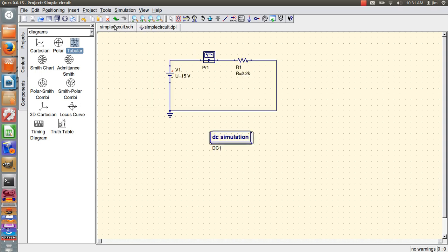and my voltage 15 volts, 2.2 k ohms, so just under 7 milliamps, which would be about right if I multiply it out. And that's how you do it.